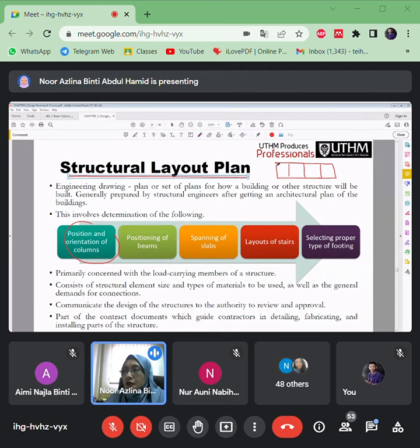the architect will mention this is the point for columns, this is the point for columns. Mostly the columns will be provided at the corner. So that's the first tip: columns should be provided at the corner. That corner is actually the intersection of brick to brick. Same goes for this T intersection here. This brick, this brick, this brick, how to tie all the directions of the brick? It should be based on the columns.